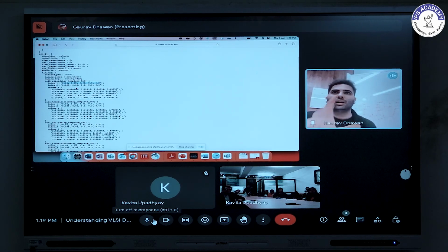Try different slew and load conditions between 0.06 and 0.12. You may increase or decrease the number of slews, but the range will be given by the design team. Even the load data will be given by the design team, and we feed these inputs to the characterization tool. The tool will know what input slews and output loads to apply to get this data. Does that answer your question?